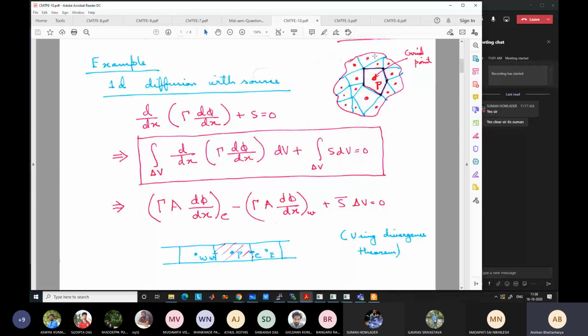It's like you are watching a movie or a YouTube video at 480p or 360p resolution, and the same YouTube video you are watching at 1080p resolution. Okay, it's a similar type of thing. At 360p, you are dividing the domain into 360 vertical pixels, and accordingly you can scale the number of horizontal pixels. And for 1080p, you are dividing the domain into 1080 vertical pixels. It means 1080 vertical control volumes, you can say, for the 1080p video. And similarly, along the horizontal, you have 1920 grid points. So your ultimate resolution is 1080 into 1920.